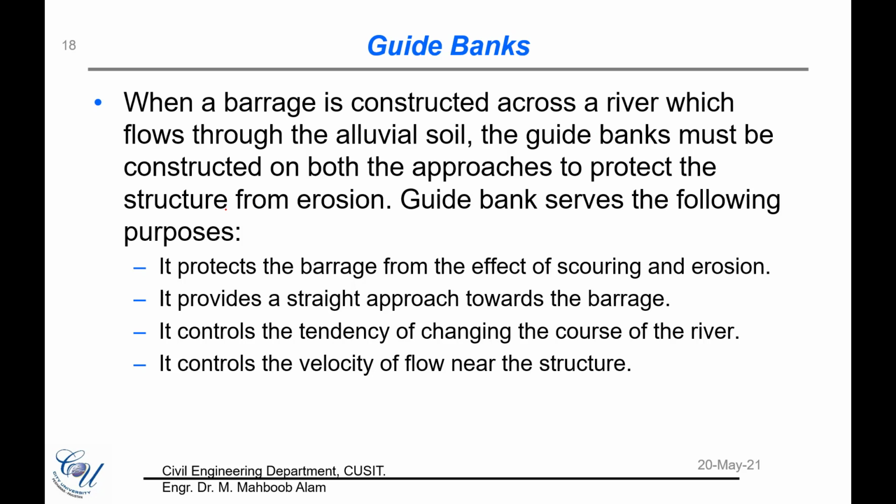Guide banks are constructed just upstream of the diversion headwork. They are constructed there so that we can protect the important structures from erosion, and the water entry into the regulators is smooth and axial. It not only protects barrages from the effect of scouring and erosion, it also provides a straight approach towards the barrage.